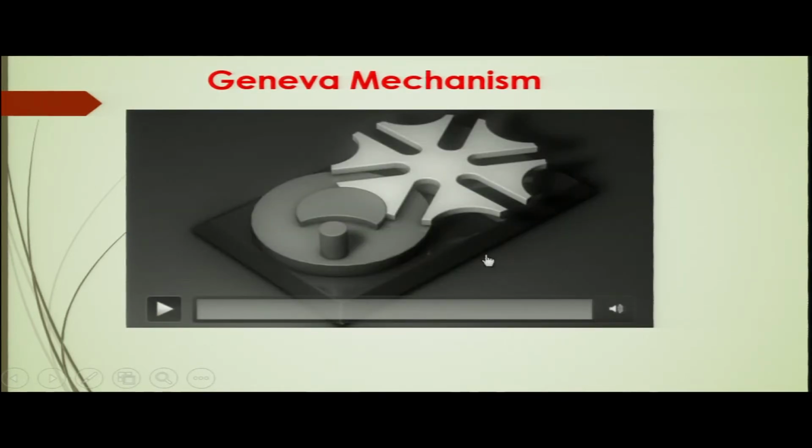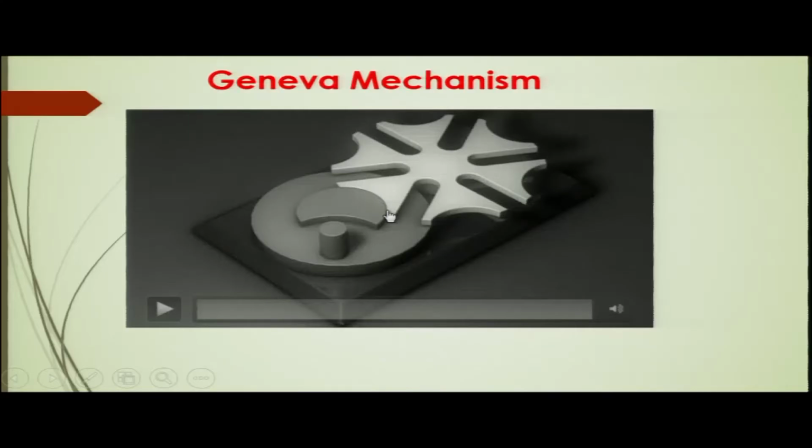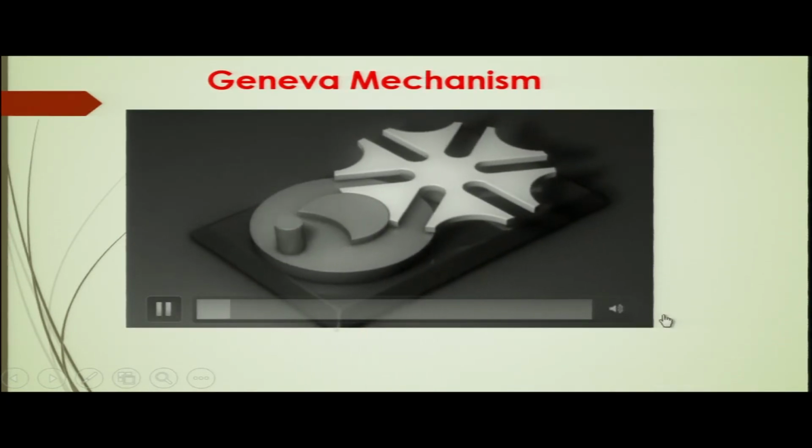All right. This is another mechanism for transmitting power from the input to the output shaft, the Geneva mechanism. The Geneva mechanism is one of the most popular mechanisms when a continuously rotating input shaft has to transmit power to an output shaft which should rotate not continuously but intermittently. As you can see here, the entire thing is the Geneva mechanism. This is the Geneva wheel, and this is the pin. The pin sits on this disc, and the disc rotates continuously, and while rotating, the pin goes inside the slot of the Geneva wheel and comes out.